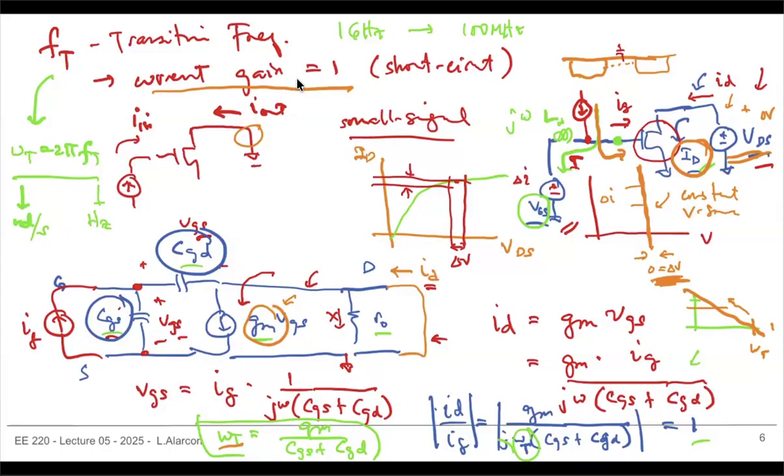Okay, good. Any questions here? Hopefully this is clear. We just looked at small signal and then at one very important metric for a single transistor. Obviously, when we start building circuits, we have other metrics like bandwidth or gain bandwidth products. But it's very important that for each individual transistor, we use them in their usable frequency range, and we'll see how biasing affects that, and how layout should affect that.